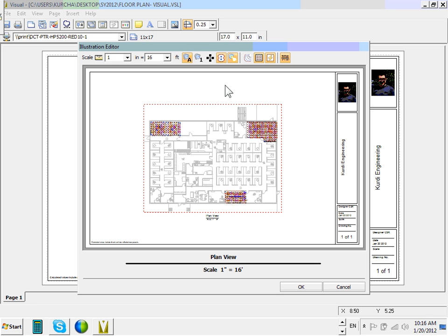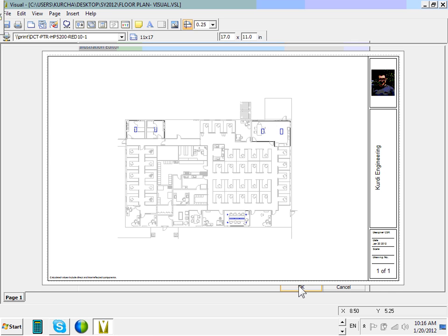Cool. The other thing is you can make the calculation disappear. If you click on this, look at that. Calculation disappears, calculation appears. In this case, I want the calculation to appear here, so you leave it as is. Scale, you can do a lot of stuff here. What else? Fill luminaire. The most important thing here is to put the luminaire label. Make sure that luminaire label is clicked. When you're done, hit OK.